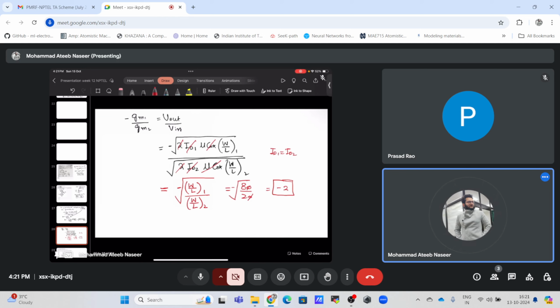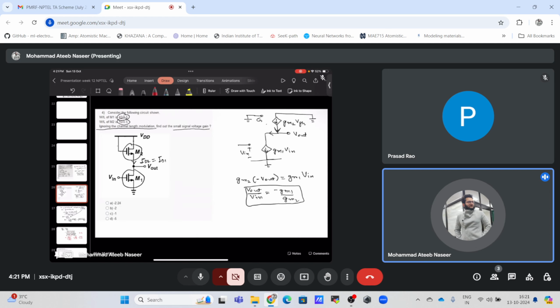What we have derived in this case is gm in terms of the current, and also we found out that if we have this diode connected load with our M1 amplifier, where the source is grounded, and we have this common source configuration, with no resistor connected to the source or the gate, the voltage gain or the signal gain is simply equal to minus gm1 upon gm2.